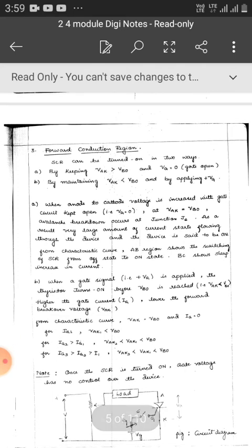The highest voltage to be sustained in forward blocking mode is the forward breakover voltage. When the voltage increases above VBO, the thyristor goes into forward conduction mode. So even if the gate drive is not applied, the thyristor is not damaged; if the voltage VAK is greater than VBO, it is rather turned on.